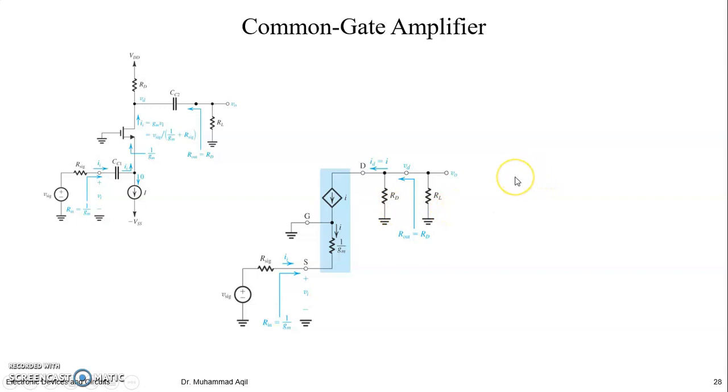And then when we put in VGS, which has a minus sign itself, as already told, we get the relation as positive, as we found in the common base amplifier. It means the common gate amplifier also, like the common base amplifier, does not invert the phase of the output as compared to the input. It means the output is in phase with the input signal, right?